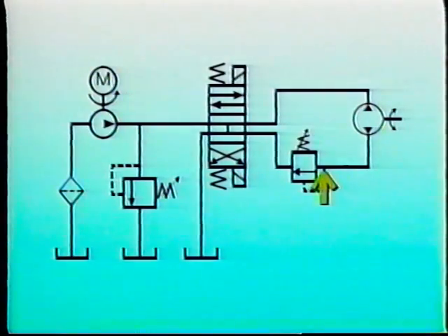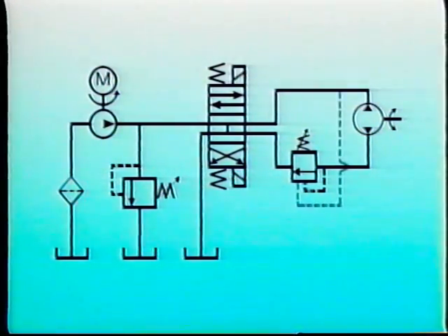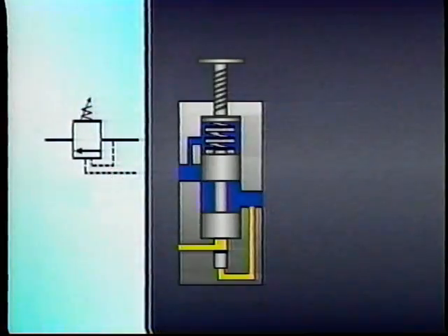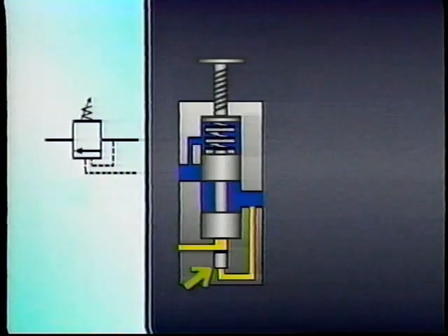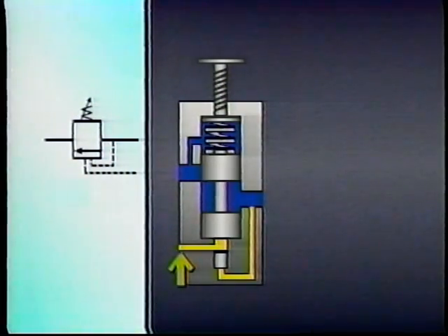Counterbalance valves are also used with hydraulic motor circuits to apply back pressure to the motor to control the momentum of the spinning load. This is commonly done with a brake valve. A brake valve is operated both directly and remotely. It has an adjustable spring which biases a spool that controls flow between the primary and secondary ports. The spool can be moved either by a separate piston that responds to internal pilot pressure at the valve, or by pressure applied to the spool by a remote pilot line that senses pressure just upstream of the motor.